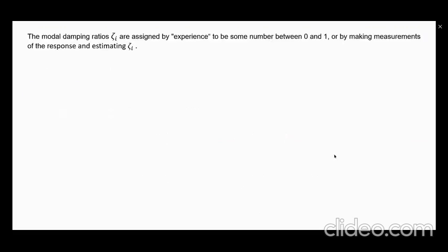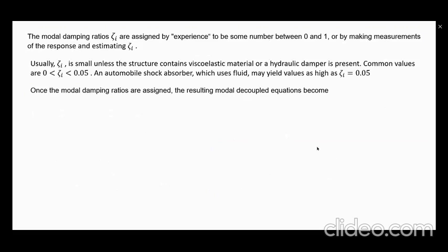Okay? So what we're going to do is, because we know that in a realistic problem there is damping involved, and based on experience, damping is something obviously less than 1, because otherwise it's not an underdamped system. Basically, it doesn't oscillate. So typically for a structure, the damping may be 0.05, 0.01, something like that. It can be higher. I'm just talking about typical, realistic values.